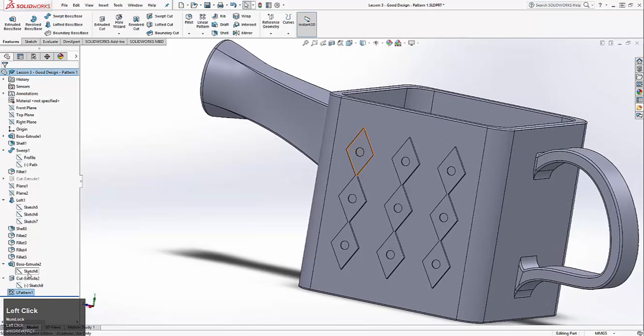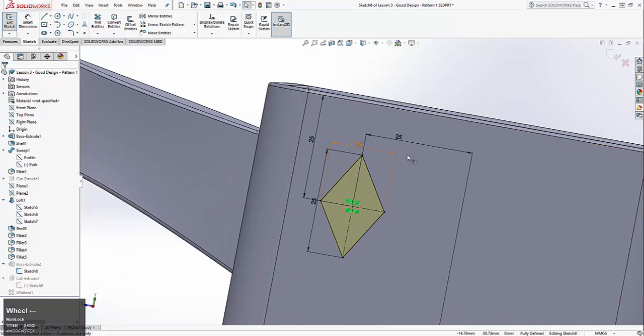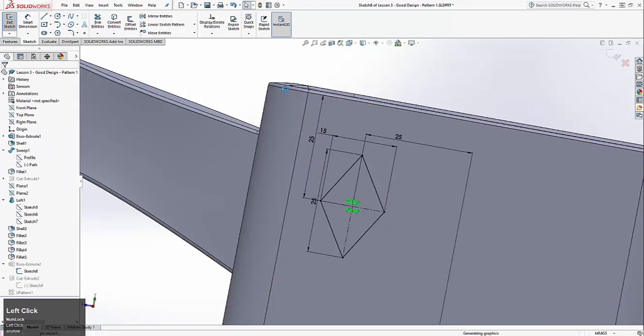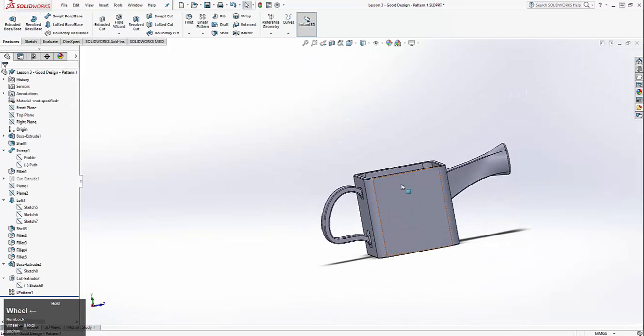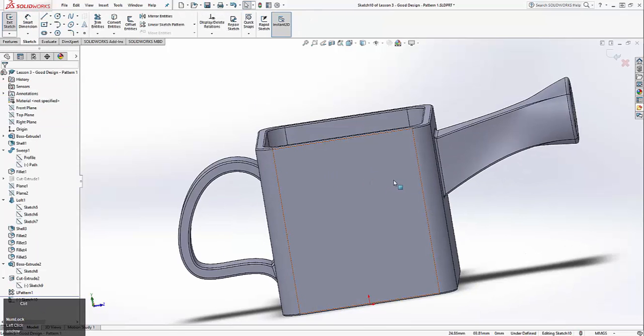Actually, first I want to get the diamond here because it's a good diamond, and I don't need to bother remaking it. So I'll just select that and copy it to the sketch. So your normal Control C. We'll come over here, do an extrude, paste that right there.